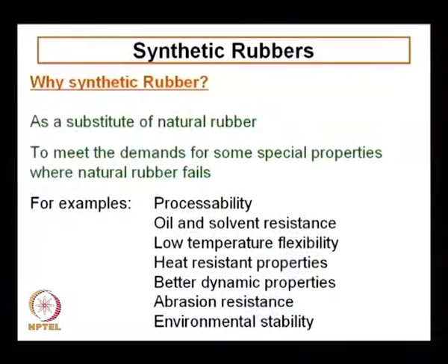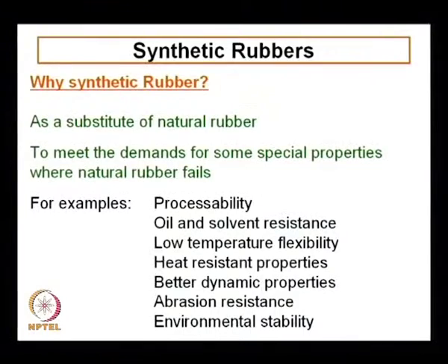those oils. So, this is one property, and there are certain applications for high temperature sealing in oil environment. So, the environment is high temperature as well as in contact with some petroleum oil, there you have to use special purpose rubbers like silicone rubber or fluoroelastomers, which will be suitable there. Okay. So, this way we go for special purpose rubbers depending on the properties we need.